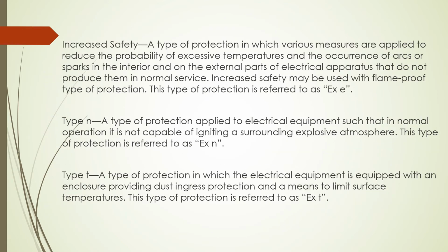Increased safety, a type of protection in which various measures are applied to reduce the probability of excessive temperatures and occurrence of arcs or sparks in the interior and on the external parts of electrical apparatus that do not produce them in normal service. Increased safety may be used with flame-proof type of protection. This type of protection is referred to as EXE.